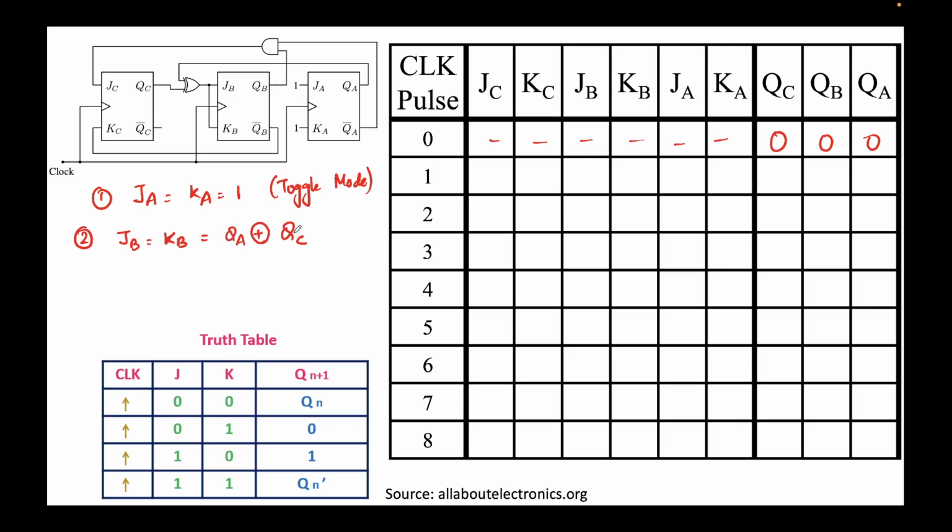You remember one of the properties of XOR is that the output is high only when exactly one of the inputs is high. If both the inputs are 0, the output is 0. If both the inputs are 1, the output is 0. Only when exactly one of the inputs is high in a 2-input XOR gate will the output be high. You can see that truth table in the second or third slide of this class itself, and we also talked about it in the previous session.